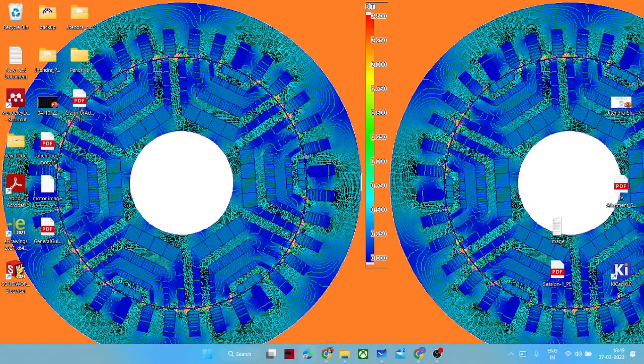Sir, by doing that charge balance, what we intend to do, sir? We are intending to compute our ripple in voltage. So basically, ripple in voltage, either you can compute from charge balance or you can compute it from capacitor current.